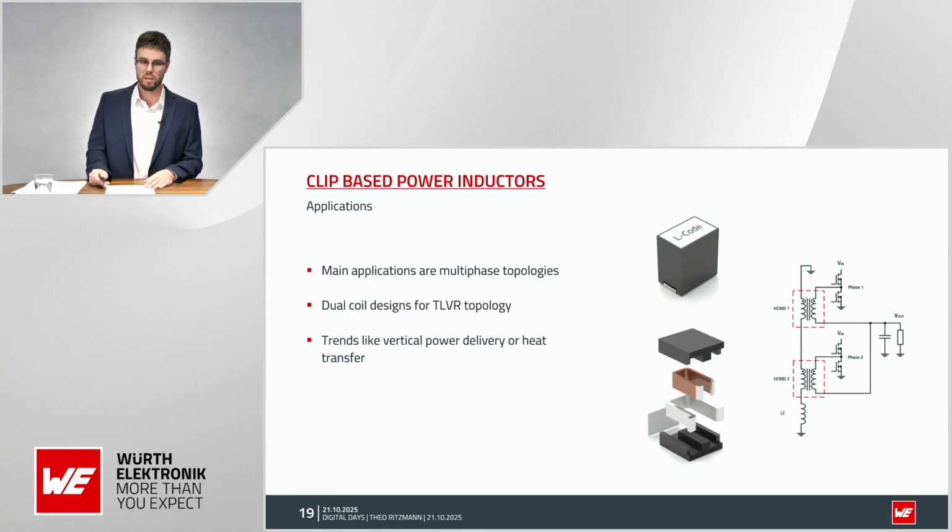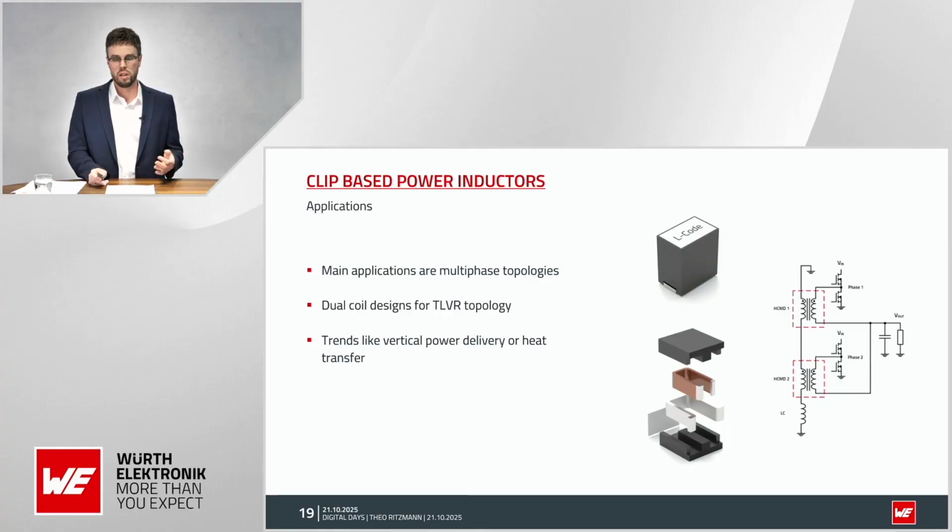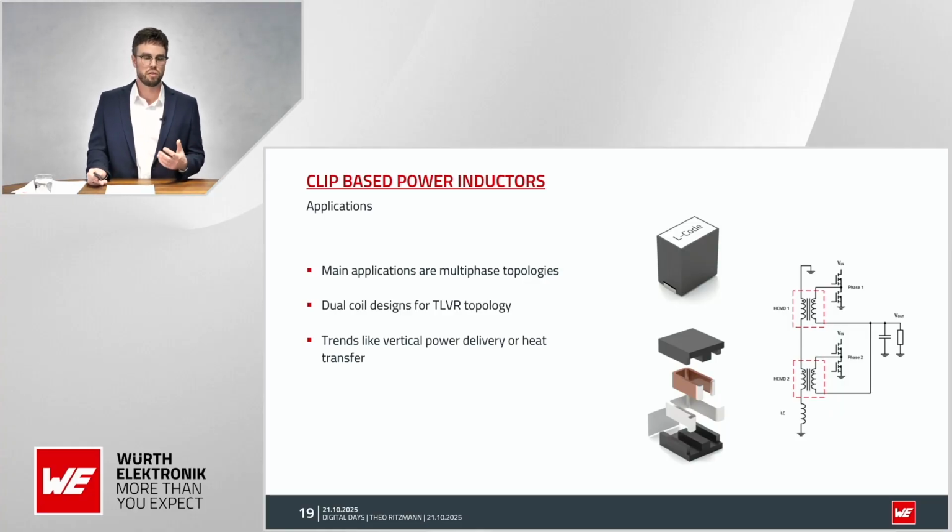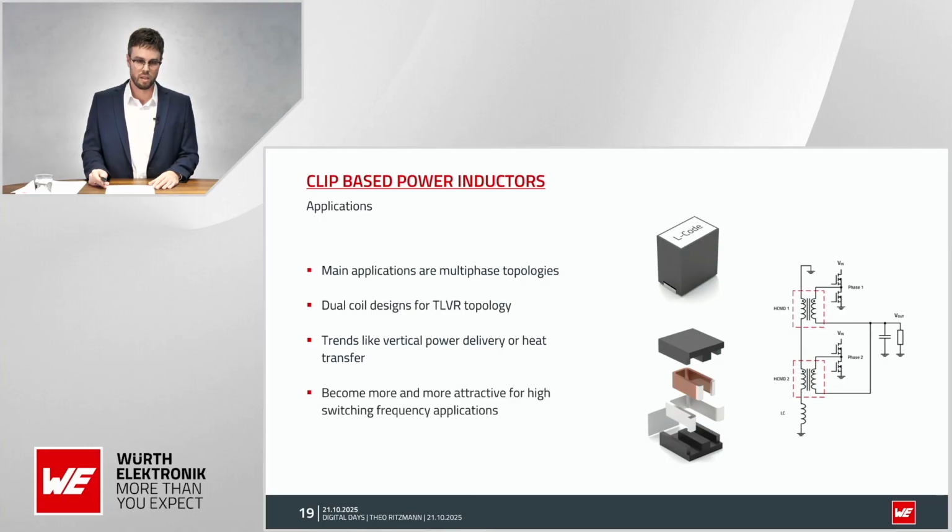For example, vertical power delivery is currently a trend, or also using the inductor additionally for heat transfer. And as said, as switching frequencies are increasing, these clip-based power inductors could become more and more popular also for, let's say, standard converter applications, not only multi-phase.